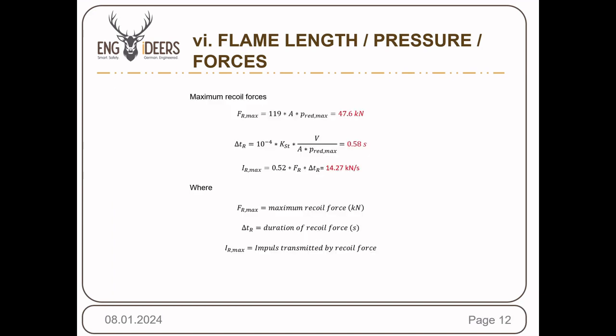And for original equipment manufacturers, if you are manufacturing dust collectors, let's say, then you also need to take into account that there are certain recoil forces caused by the explosion. These recoil forces can also be calculated using these equations, which is the FR max. We use the vent area and the P red max to calculate the recoil force, so the maximum recoil force.